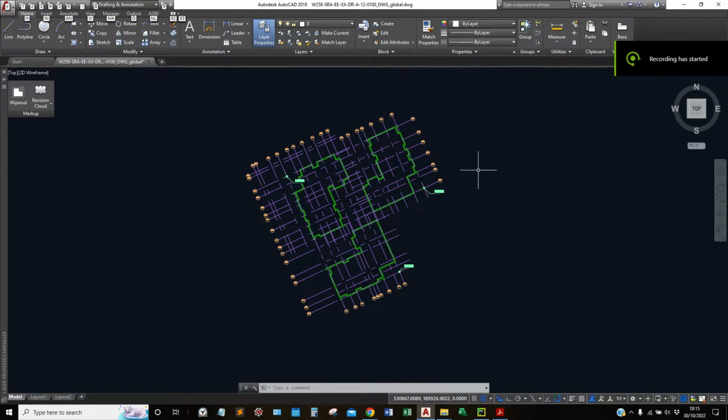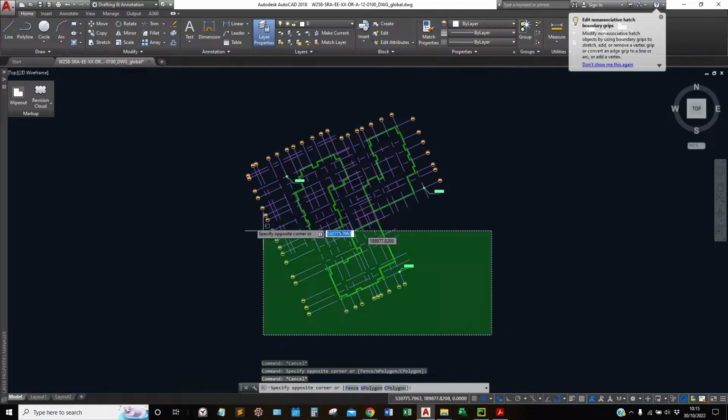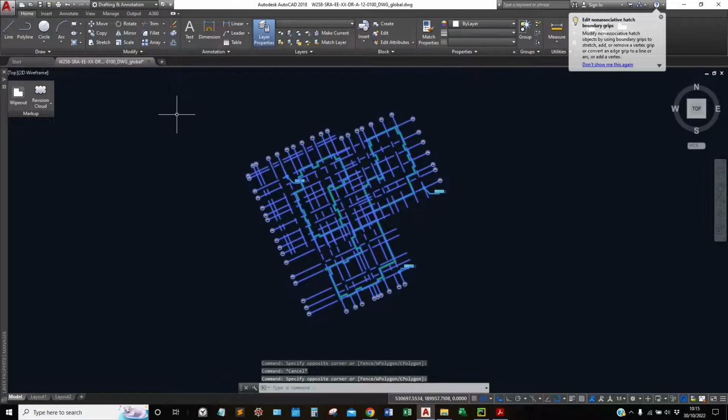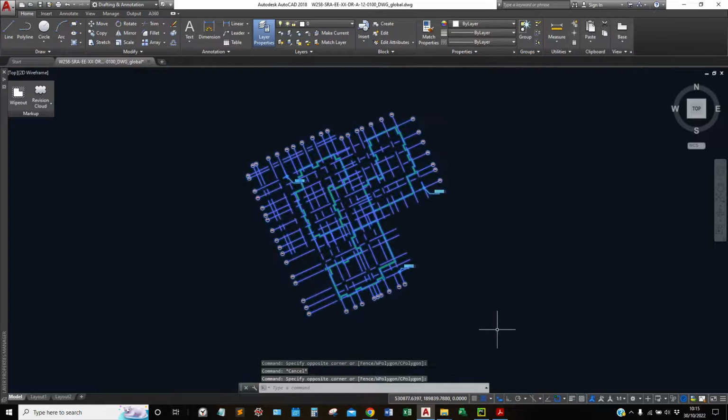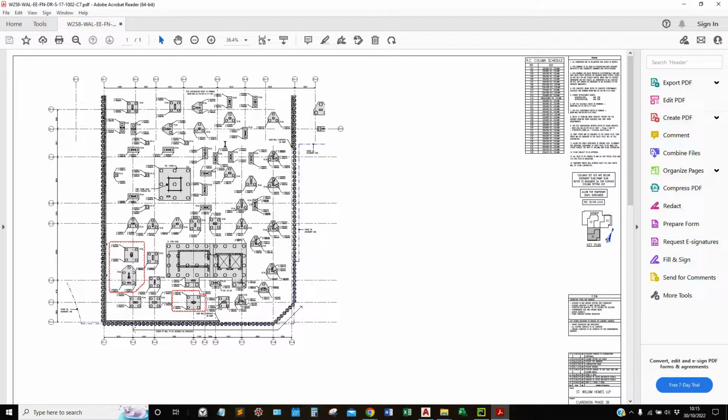I'm going to show you how I can use this coordinated grid line drawings from previous videos. Have a look at that one. How I can use these coordinated grid lines to coordinate any of my drawings. So today I will use these foundation drawings with pile caps, core caps, and align these drawings so I can use it effectively and extract information that I need to set out.